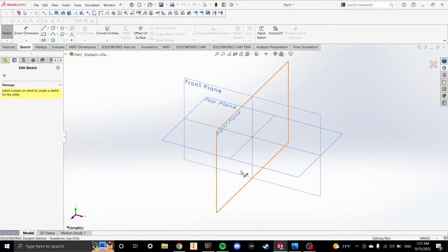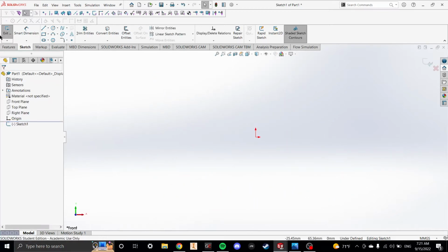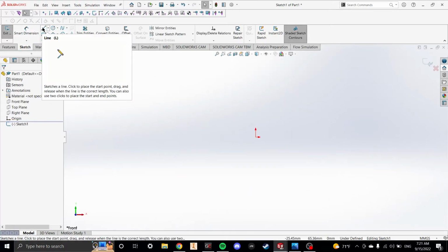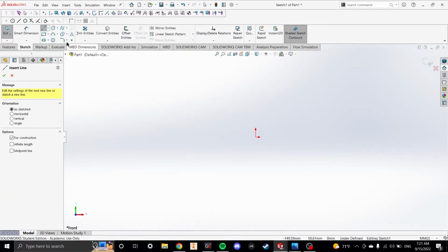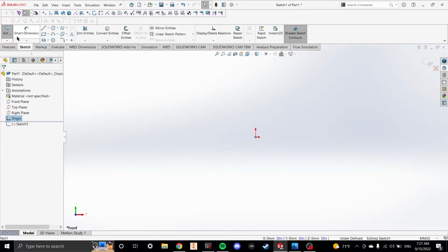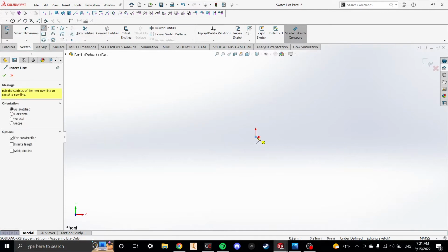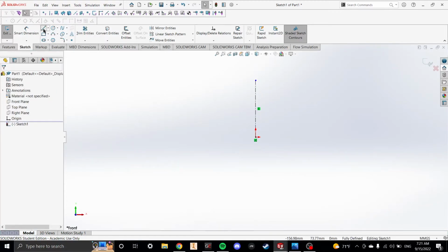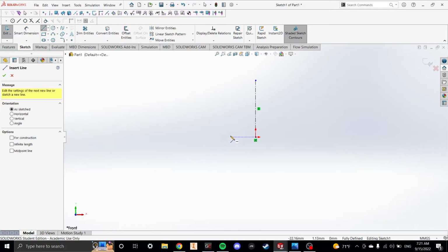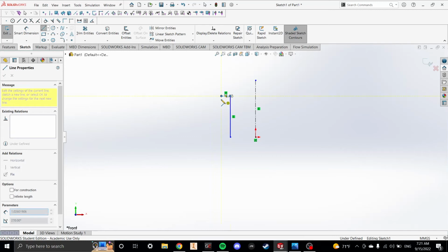click on the sketch thing, and it'll ask you which plane you want to do the sketch in. This is very similar to Inventor, but you're just going to click on the front plane, and then you can start your sketch. I want to revolve around a center line. If you go up and click line, one of the drop downs is a center line, and that's basically like a construction line in Inventor, but it just allows you to make a line without really including it in the part. You'll just do a vertical line, arbitrary length, doesn't really matter. And then you can just do a regular line off of that, and we can stair step down like the part looked.